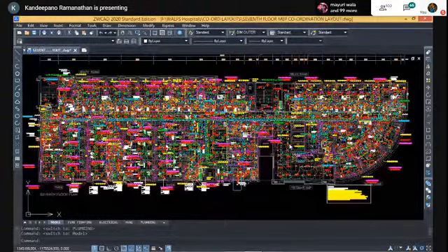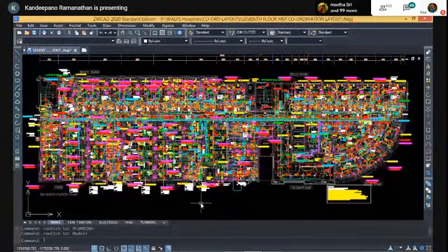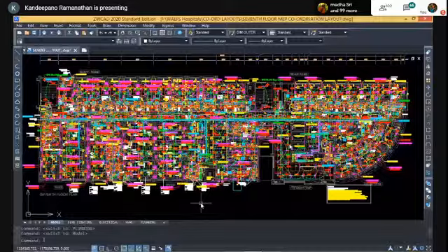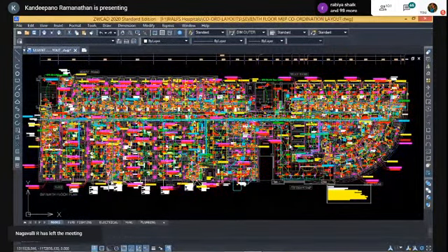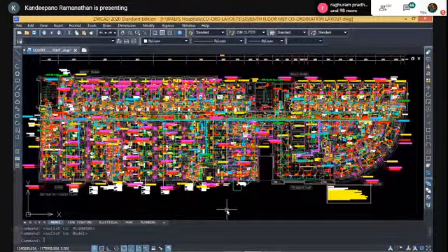This becomes the most complicated one, right? Now, as you look at it, you can't understand anything. Just now when I showed you individual services drawing, at least you can see something. But here, you can't comprehend most of the things because everything is falling one above the other. Now here only we have to get inside in a microscopic view format and then coordinate amongst the services so that clashes are not there.